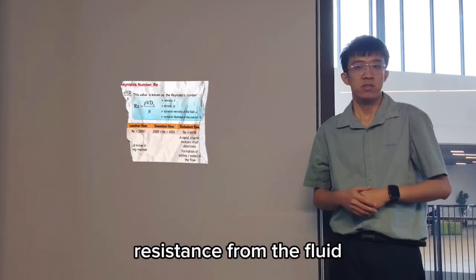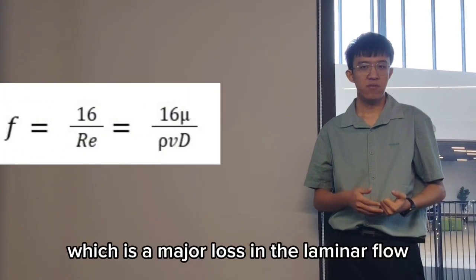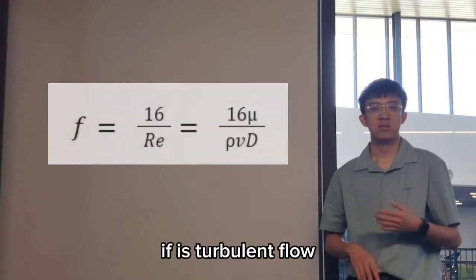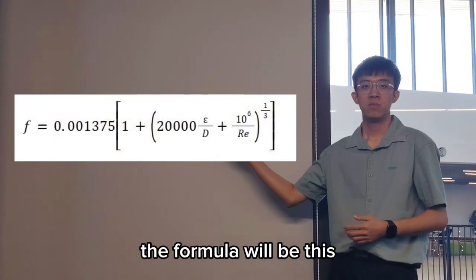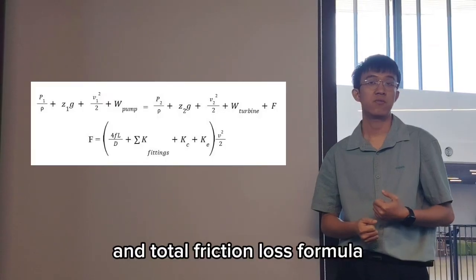Resistance from the fluid friction and pipe wall roughness causes the pressure drop, which is a major loss. In laminar flow, the friction factor formula is as below. If it is turbulent flow, the formula is this. If it is transition flow, the formula will be this. Other than that, we also use the Bernoulli equation and the total friction loss formula.